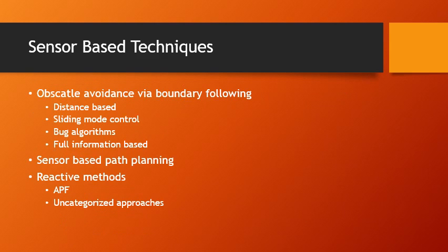Sensor-based techniques for navigation commonly employ local knowledge. Global sensor-based planners use sensory information to build a comprehensive model. In local path planning, onboard sensors are used to locally observe the nearest fraction of an unknown environment. In obstacle avoidance by boundary following, unlike common algorithms that avoid obstacles, a boundary condition is held and stays satisfied. Boundary following is a self-contained navigation of immediate interest.